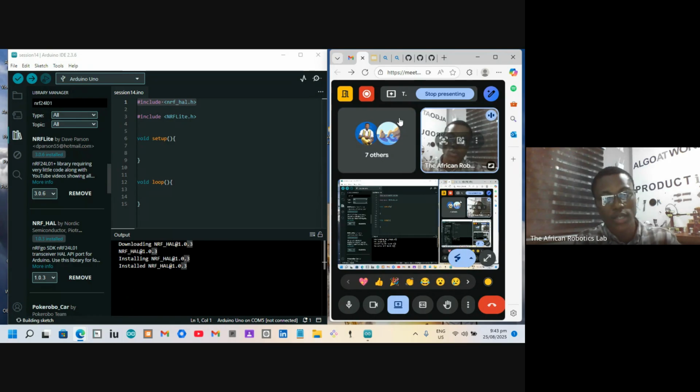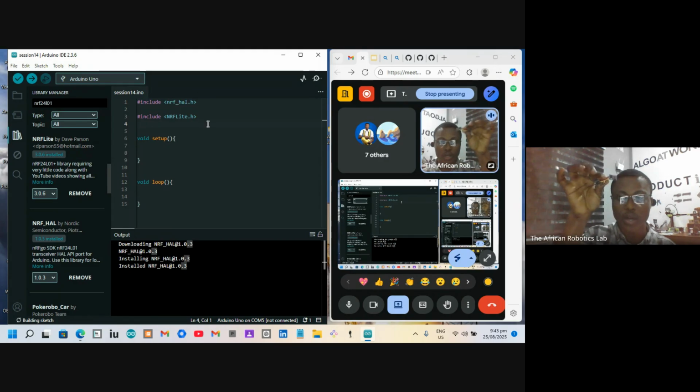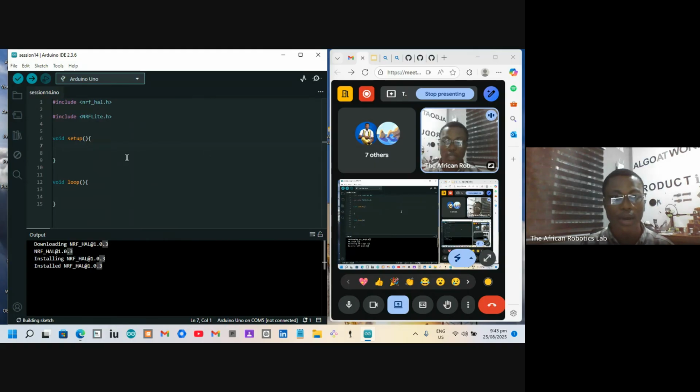There are certain keywords in it. How do you use it? You just add the library in here, and then you create an object. You give it a special name for your particular component. If this is the first component, the second component, you just give it a special name. Then for some libraries, you have to initialize it, like we saw on there, wire.init, and you put the pin numbers in there, and it's going to start the communication between the microcontroller and this component. But we're going to be taking a look at all of these things.